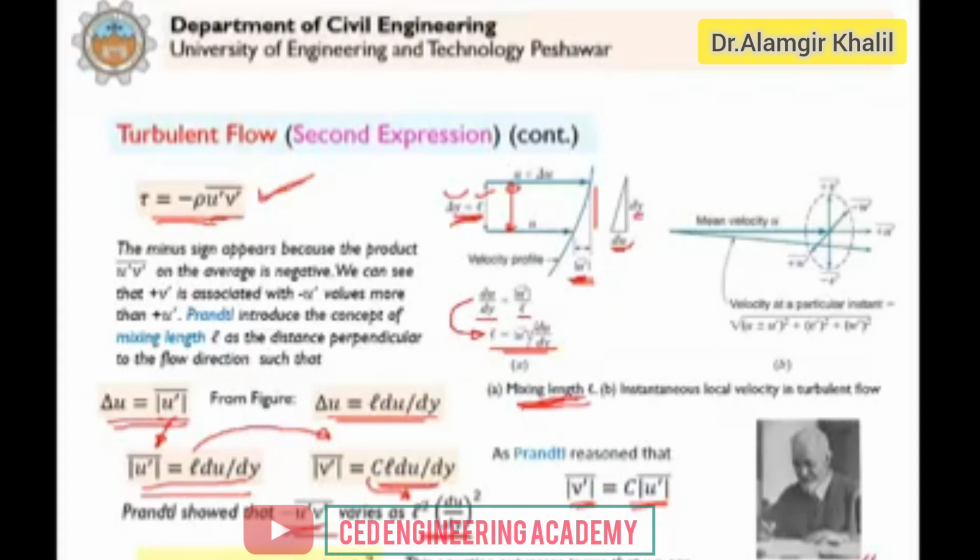So now the shear stress, which was represented by this Reynolds stress, is now represented in this term. And now this form of the shear stress we can measure. This we can measure because this L we can now measure, and this can be represented as a function of the pipe radius. So the shear stress you can easily calculate. You have the head loss, and then from there we can easily calculate the pipe wall shear stress. Clear?